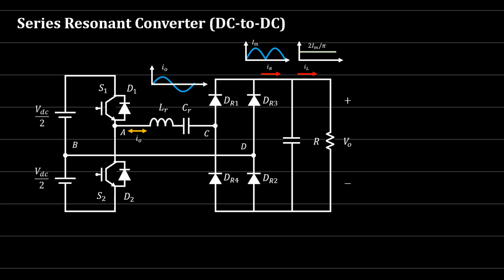And if you think about the DC to AC converters from the resonance point of view, you will find that there are not many applications that can be applied using the inverters, right? Because the main idea for the resonant inverters, or the resonant converters in general, is that we operate at a certain frequency. We operate at the resonance frequency, right? And this resonance frequency is not always there. Sometimes this frequency is 100 Hz, sometimes 1 kilohertz, sometimes it's 2 kilohertz.